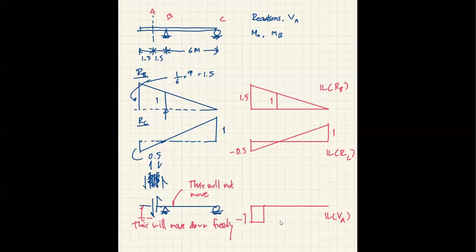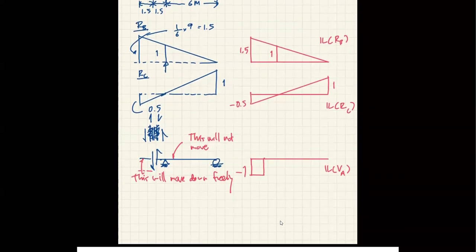Once the load travels over part A to somewhere beyond A, before B, or after B, the presence of the load on the right side will not shear part A off, right? And this is what I like to call talk to the structure. If you can see how the load is going to affect your structure, that is talking to the structure.